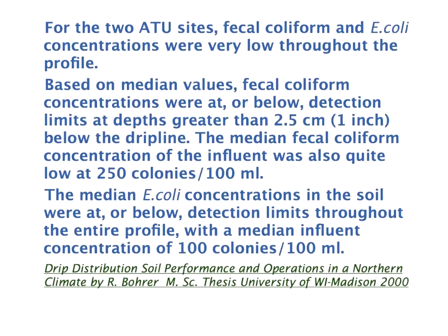Now, in her dissertation, she does deal with septic tank effluent, and she does deal with a lot more. But the fact is that, particularly with secondary treatment effluent, the treatment takes place very, very close to the dripper. And so the question of how far you need to be above the water table becomes a question of regulations, not a question of engineering.